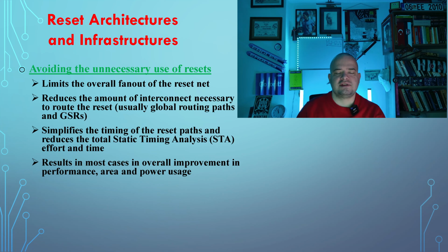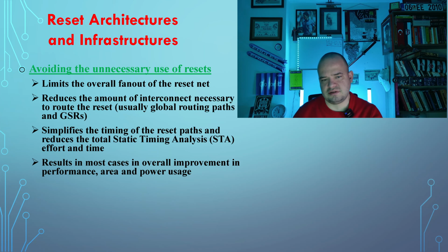Since effort is less, the total time you wait for the compilation will also be less. So it reduces total STA effort and time. And finally, those result in most cases in overall improvement in performance, area, and power usage. So you are winning a lot if you avoid the unnecessary use of resets.